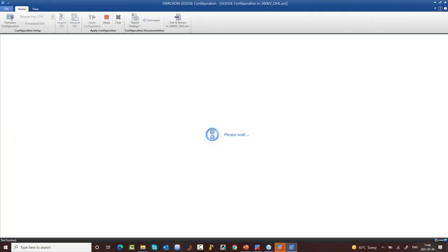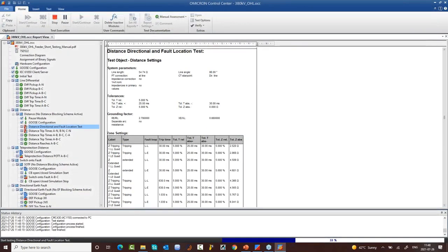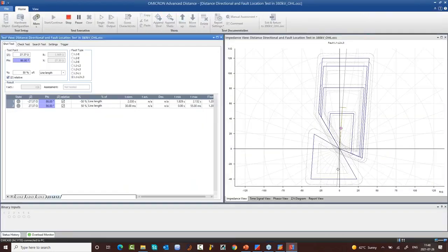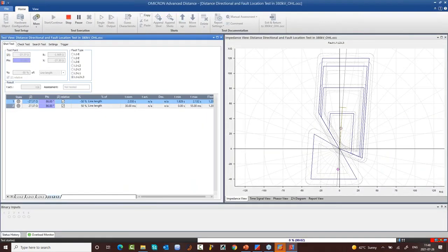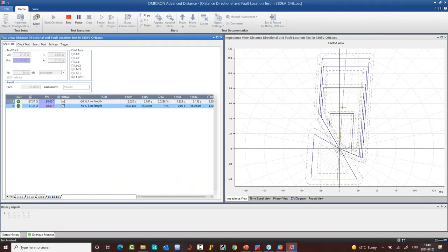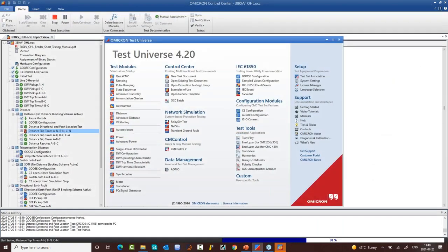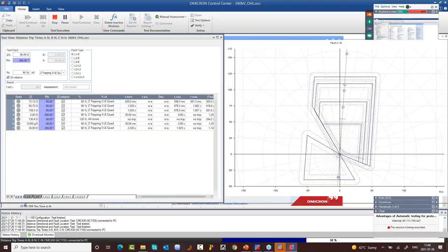This test module, or command, you can include in your OCC file. It will open third-party software, for example, relay software. Maybe you would like to change a setting. Maybe also you can open IEDScout. I did it before in some other webinars to change the status of a circuit breaker, for example, or doing some simulation. This can help you a lot, saving your time.